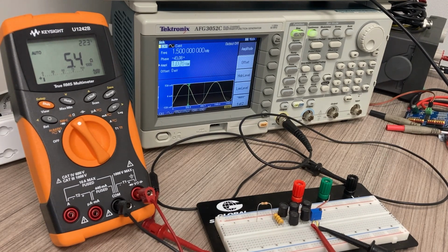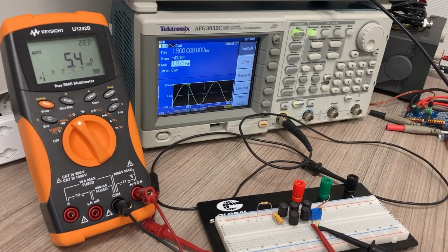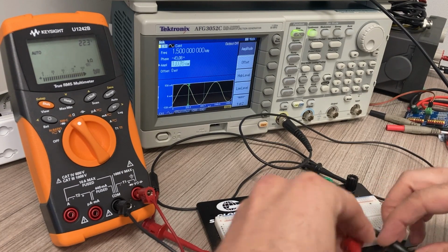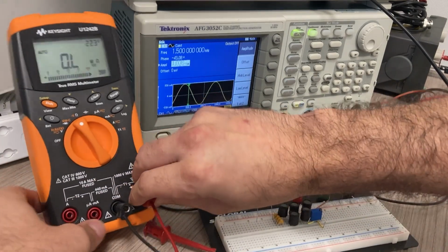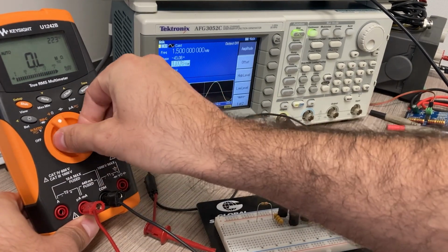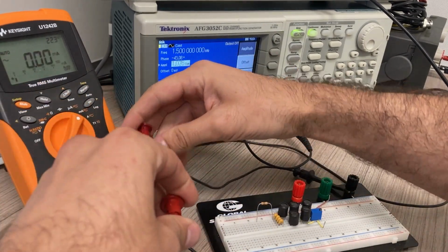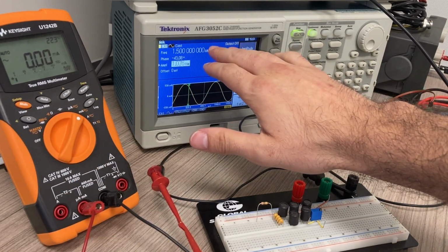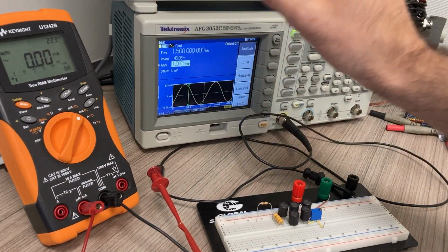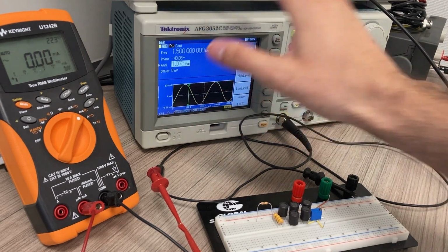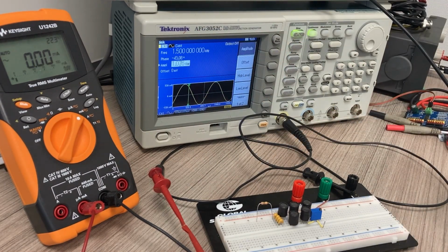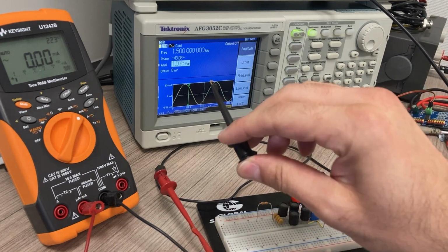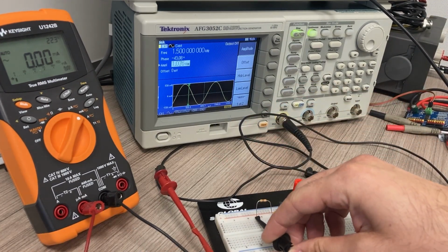All right, and I have an Excel spreadsheet open. I'm going to type in 5.4, and now I'm going to switch to a current measurement. So I come here, switch to my function generator, and of course I changed all my parameters in my function generator already. So I have my Thevenin equivalent circuit and my function generator is where it needs to be. And I connect the negative side to the front of my circuit.